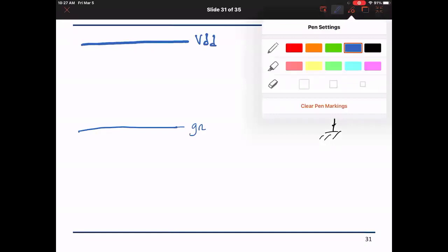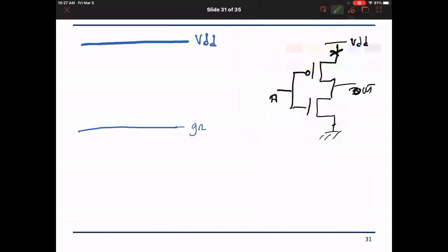Then I am going to draw a line for the NMOS transistor to represent its diffusion region, and a line for the PMOS transistor to represent its diffusion region. Now in this circuit I have the same input going to one transistor and the other, so the same poly input can connect over the two.